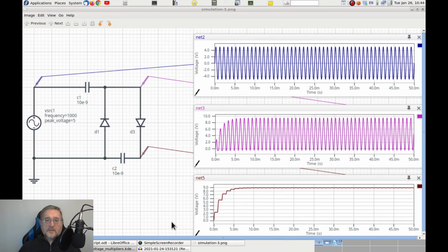The circuit works similarly to the ones we saw previously. This time, however, we don't need the square wave generator, because the power supply is already an alternate current, like the one you can get from a power outlet or from a transformer. Capacitor C1 is put in series with the generator, and the diode D1 connects the other end of the capacitor to ground. With this kind of connection, every time the generator output is negative with respect to ground, the capacitor will be charged through D1.